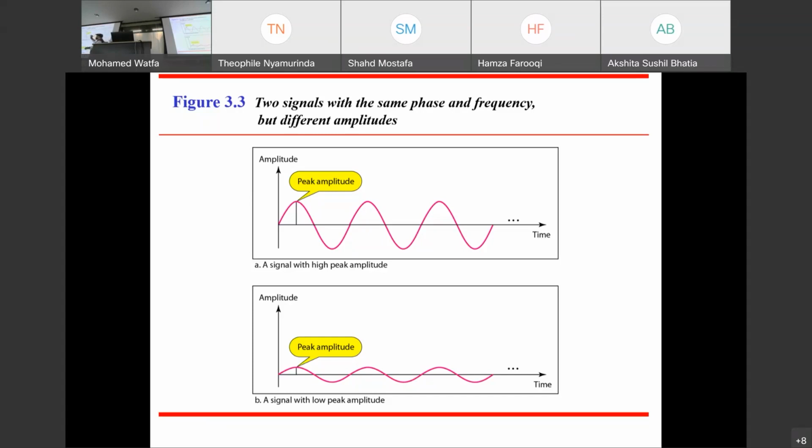Okay? So for you to understand a little bit more, by definition, period is how much time I need to complete 1 cycle. Yes, very smart. The time I need to complete 1 cycle is the period. And how many cycles per second is the frequency. You see the relationship? They're inverse, 1 over the other. Again, very simple. If my frequency is 3 cycles in 1 second, how much time did each cycle take? 1 over 3. You see? That's how we got the formula. Now we know what period means. Are we good? Yeah, let's move.